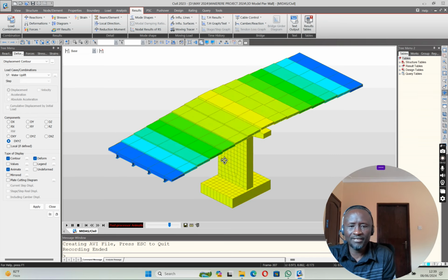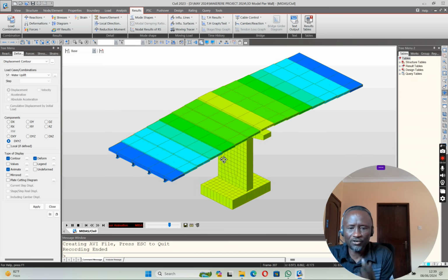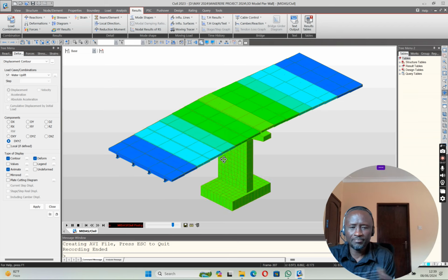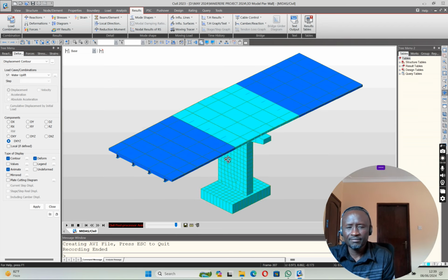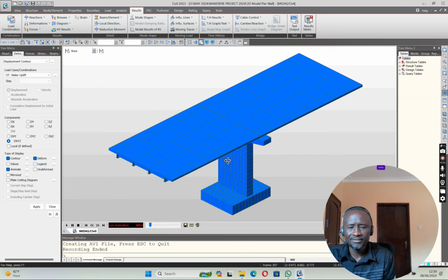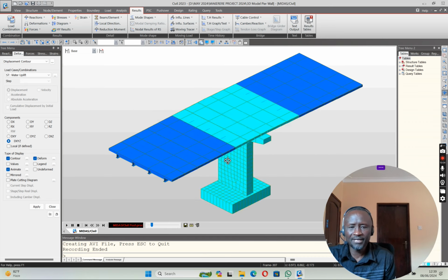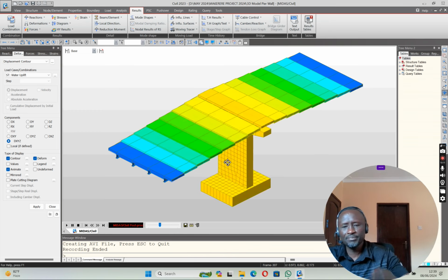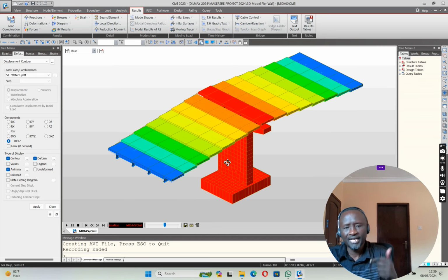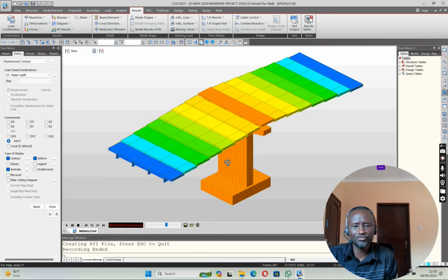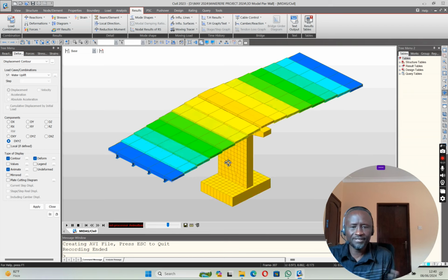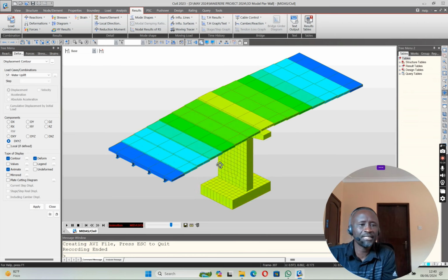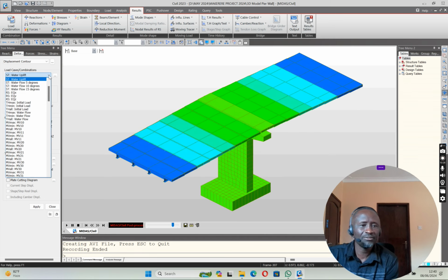We had a problem with the Katonga bridge. For Katonga, the pier was isolated. Water came and scour. Water went with the embankment, and the thing floated, and the abutment went. And then because it left a big long gap, a long span, which is like a cantilever, it went down, and the pier also lifted because I think of the scour, there was buoyancy, and the flood was too much. That's how the entire bridge came down. So that is the scenario.